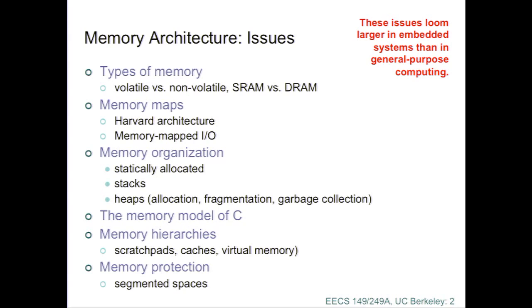Okay? Now, if you run a C program on your laptop, there's an operating system and some hardware in the way that will actually prevent you from doing a lot of stuff that you actually would like to do. So you can't necessarily access all physical memory locations. You sort of need the operating system's permission. You have to go into kernel mode to be able to access certain locations. But in the embedded systems context, often there's no kernel. There's no operating system. You control the hardware, and you can do damage. But you can also do wonderful things. And so you're really controlling the hardware.